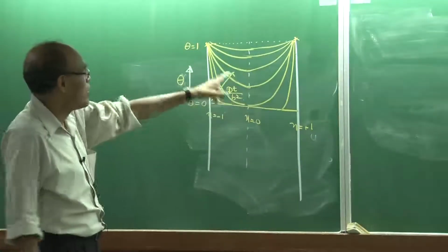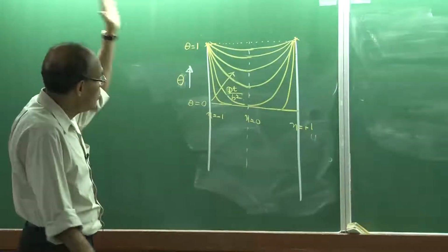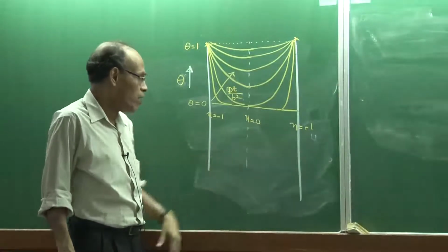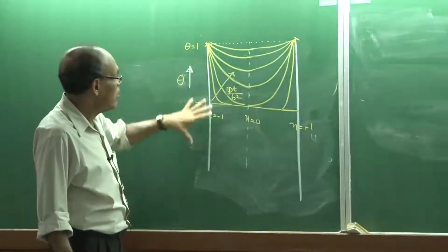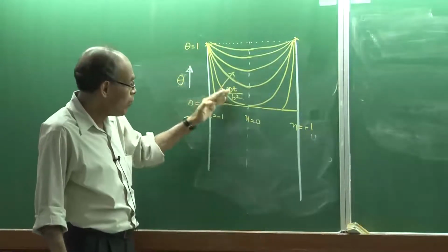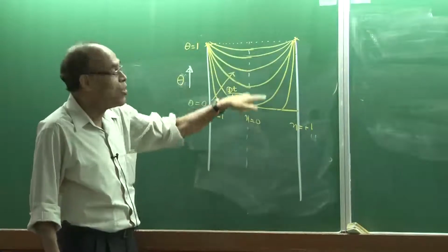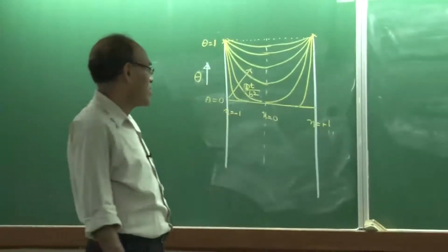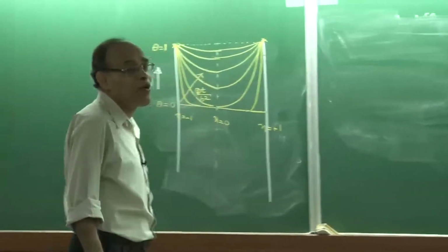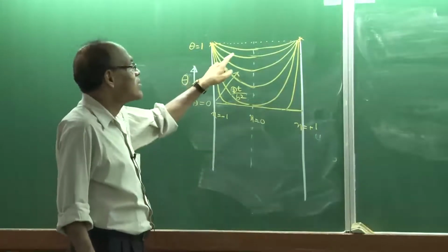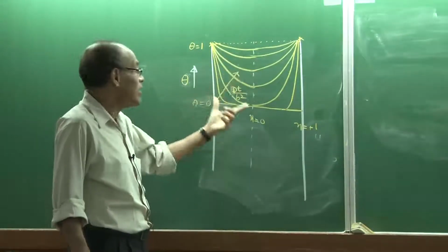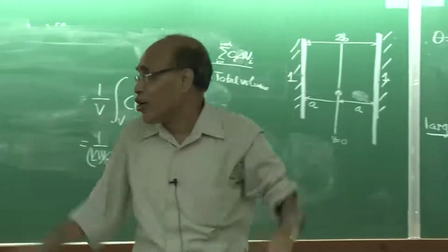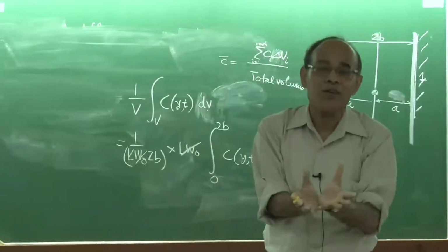We have converted the equation to a dimensionless form, and therefore everything now becomes within 0 and 1, nothing goes out. The dimension is between -1 and +1, and theta of course varies from 0 to 1, and for different values of dimensionless time, these are the curves which come out from the infinite series solution. So we may not do the infinite series solution. If we have to determine only the temperature at any point, we will straightaway refer to this chart, and an equivalent chart is available for an infinitely long cylinder. Equivalent charts are available for a sphere, regular sphere.